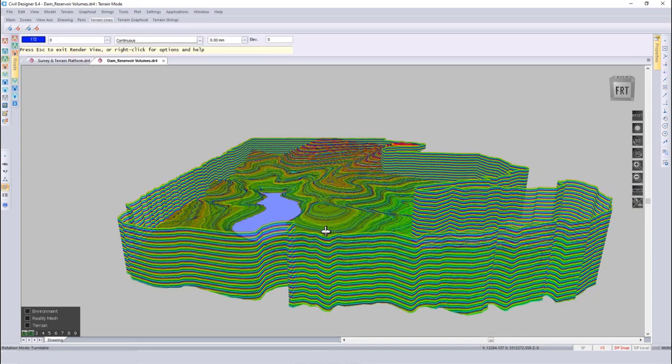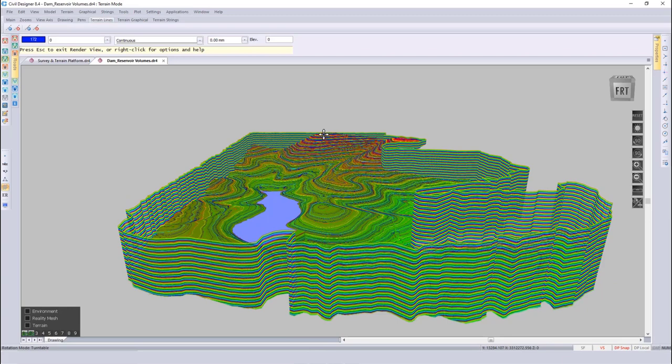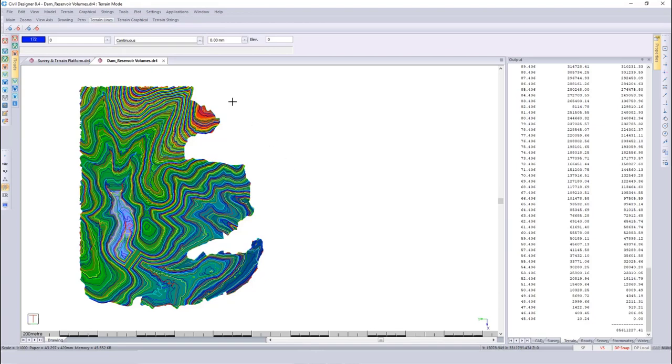And then just to right click again, render view, it helps to explain the function in a little more detail. So there we got the highest point. It uses that elevation around the perimeter of our site and then calculates the volume within that perimeter. And then close these two projects.